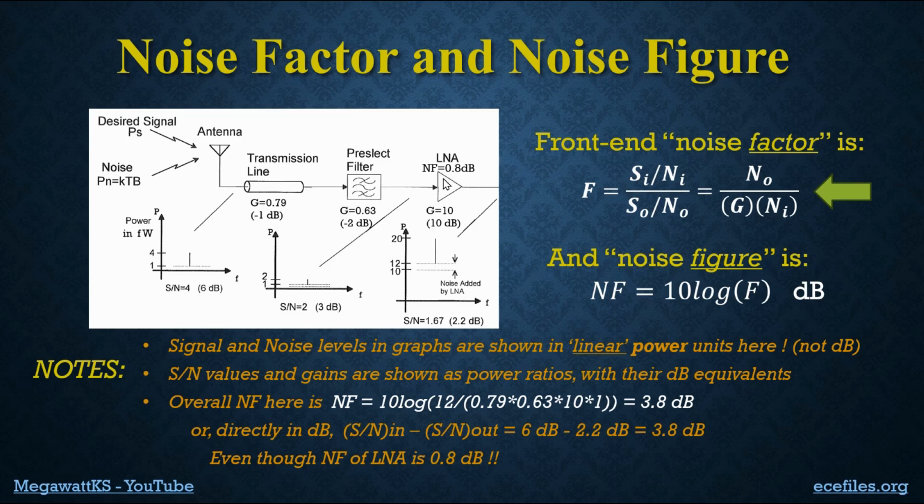Now, our LNA with a 0.8 dB noise figure did help us a little bit, because it means that we didn't degrade ourselves even further from this 3 dB. We only added another 0.8 dB from using this LNA. So a good LNA is still valuable, of course.